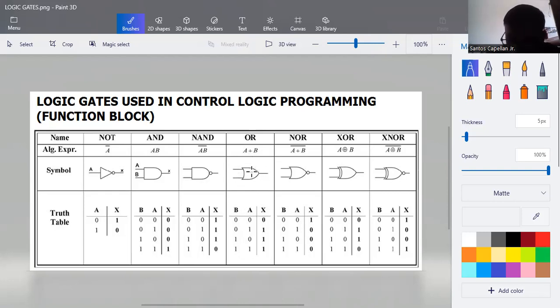Okay. So that is an OR. Now NOR, not OR. Again, you will notice this has a small circle in front of the output. So you are just going to negate the output. So 0, 0, 1, that's correct. 0 and 1, that is 0, because in an ordinary OR you will get 1, but you have a NOR, a negation here, so it will become 0.